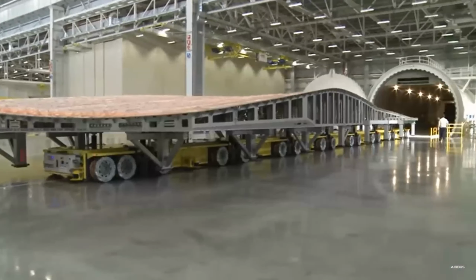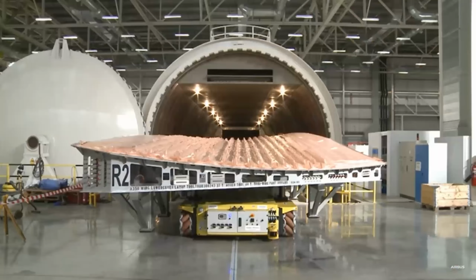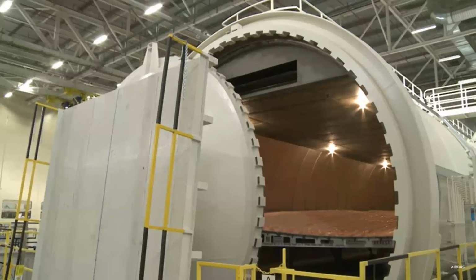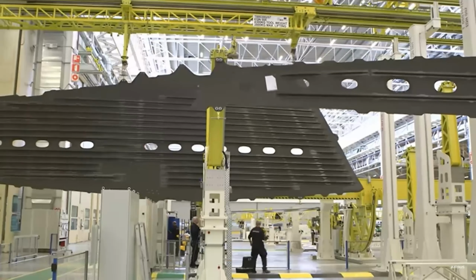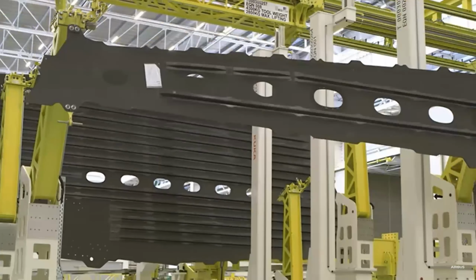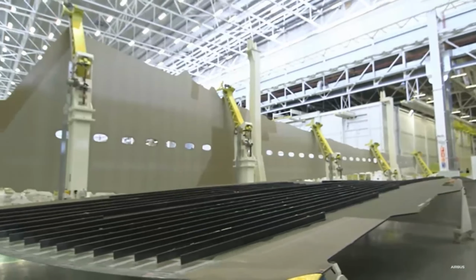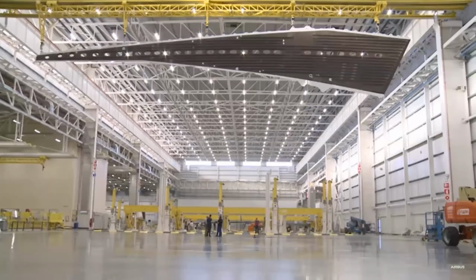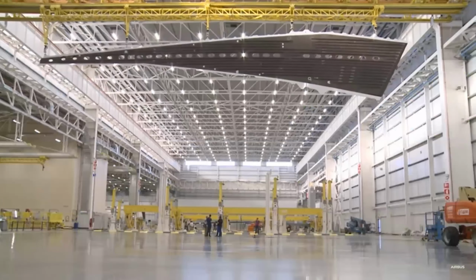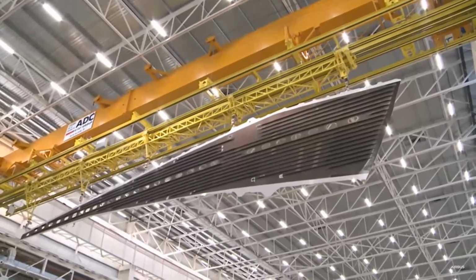After that, it's heated or cured with a resin mix in massive pressurized ovens known as autoclaves. When they emerge, the large sections are turned into light but strong composite parts. In the beginning, on the A320 program, under 10% of all the aircraft structure was made from carbon fiber. It rose to 25% on the A380, and it's now around 53% on the A350 XWB.